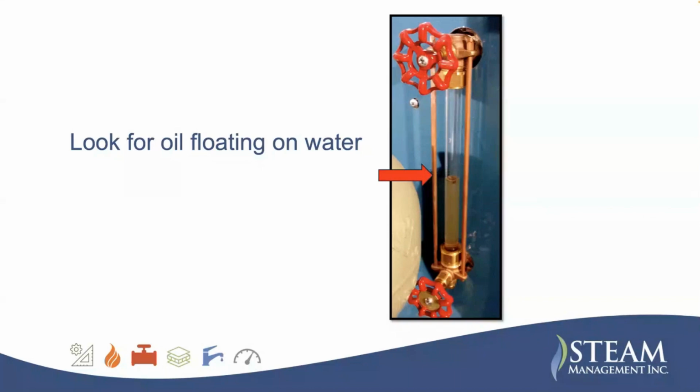Now, one of the things I'm going to caution you on is I've had boiler maintenance people drain down the boiler and then refill it with fresh water, right? Well, that oil adheres to all the metal sides on the water side of the boiler. So when you bring that water back in, it bounces right to the top of the water level and says, "Hey, I'm back." So you want to have something that's going to clean that oil. What I would do is check with the boiler manufacturer for what they recommend.